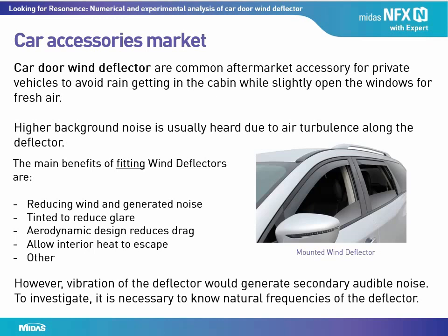Midas NFX is used to perform numerical modal analysis. In the study, the deflector model is built directly in NFX using its preprocessing tools. A physical deflector underwent experimental modal analysis. Measured data are used to correlate and validate the FEA model.